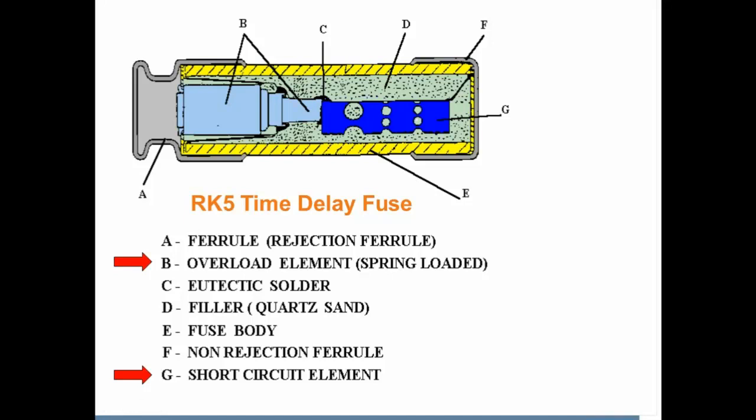So the process is they are wired in series, and when they are wired in series, if you have either section open, the fuse is open, it's non-resettable, and you throw it away and replace it with a factory fresh calibrated unit. With this, we have the best of both worlds, because this is sized maybe 10 times the fuse's rating with no intentional time delay, and this is calibrated to the fuse's rating.